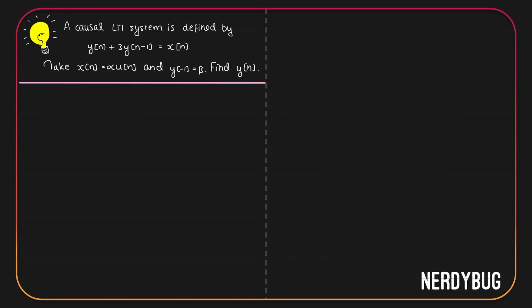Let us solve a problem based on this. A causal LTI system is defined by the difference equation y of n plus 3y of n minus 1 is equal to x of n. Here x of n is alpha u of n and y of minus 1 is beta. We have to find out y of n, which is the output of the system. Here the system is causal and the input is also causal, because it is alpha multiplied by u of n. U of n is causal, so alpha multiplied by u of n is also causal. So here we can use unilateral Z transform.